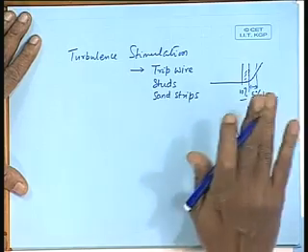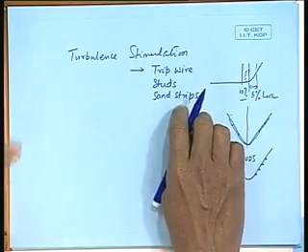Now, one has to be very careful, we are adding extra appendages to the model. As long as it is limited to only turbulence stimulation, it is fine. It may so happen that it actually adds resistance, is not it? That can also happen. If I have appendages, it may also add resistance. So, we have to make a compromise on how much turbulence stimulation has to be given, so that just about turbulence is stimulated, but it does not add its own resistance to ship resistance. So, this has to be done carefully.